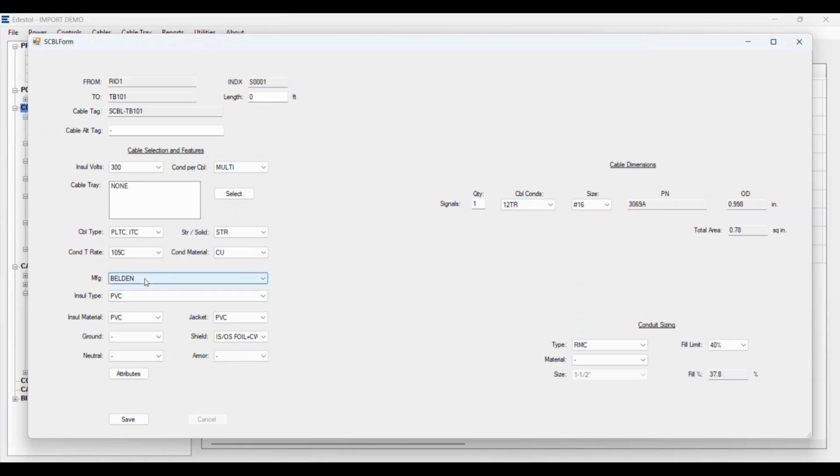You can, depends on what you select. This control and signal database of cables can get real confusing because Belden doesn't just use copper, it uses bare copper, it uses tin copper. You got to kind of know what's in your database to select what you want, because if you go to like tin copper, then you get pairs, 1 pair or 1 triad. If you've got bare copper, then you got 1 pair and that's it.